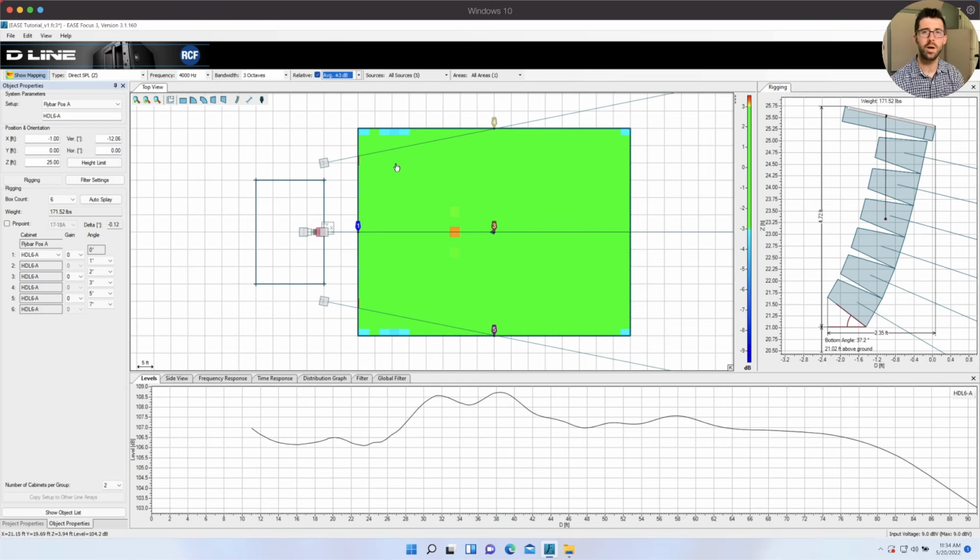So if I'm looking for one singular sign that tells me, hey, I'm done, I've done a good job, this is it. If I can get plus or minus 3 dB, 3-octave weighting at 4K, without having to do anything super crazy to my array or have a bunch of overlapping stuff. It's not like just make it green and you go. You have to have some understanding of other rules too, but I really like this feature. It is the relative feature.